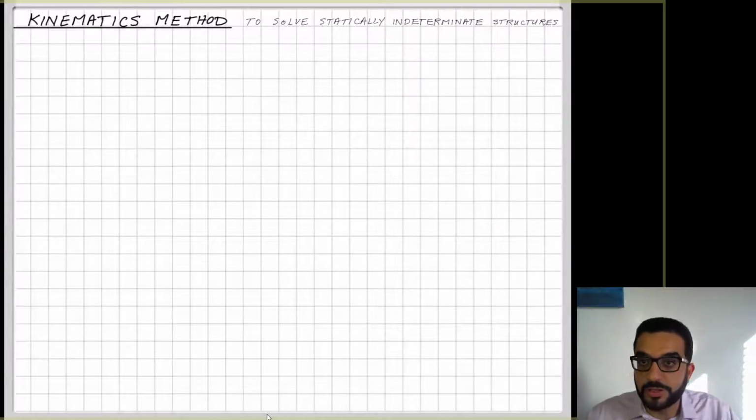The last part we learned about the redundant force method. Using superposition, we can analyze a member under axial loads by taking out one redundant reaction, and that would be a case under the external loads, and then analyze another case when we have the redundant support reaction put back, and we apply the rule that the summation of the deformations should comply with the constraint of the original redundant reaction that we have in place.